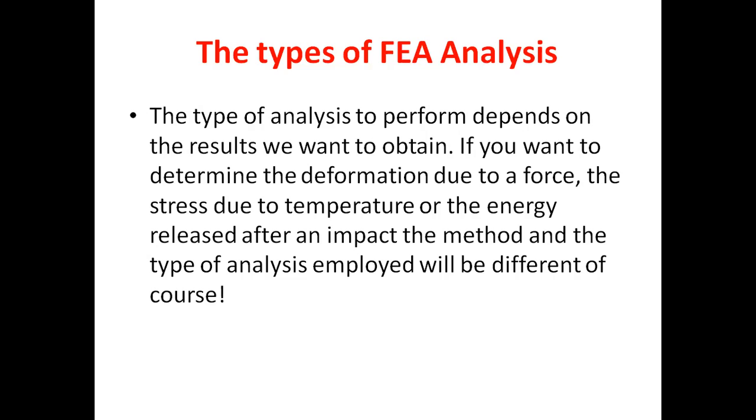If you want to obtain stress and strain, it is a static analysis. If you want the temperature result with the effect of time, it is a transient thermal analysis. If you want a time dependent result with force and other factors, then it is a dynamic analysis. If you want the result of your vibration, it is a modal analysis. These are the various types of analysis.